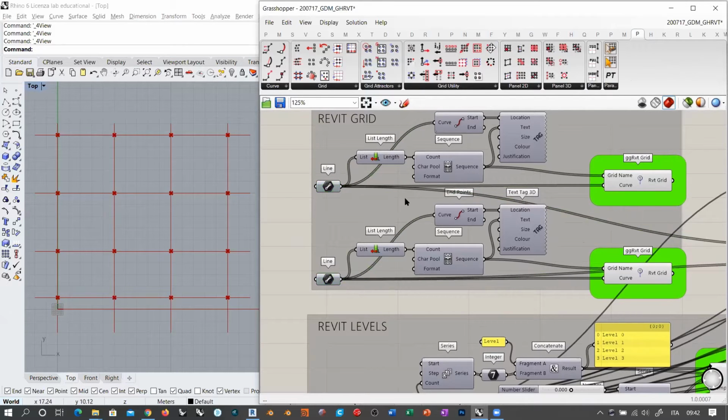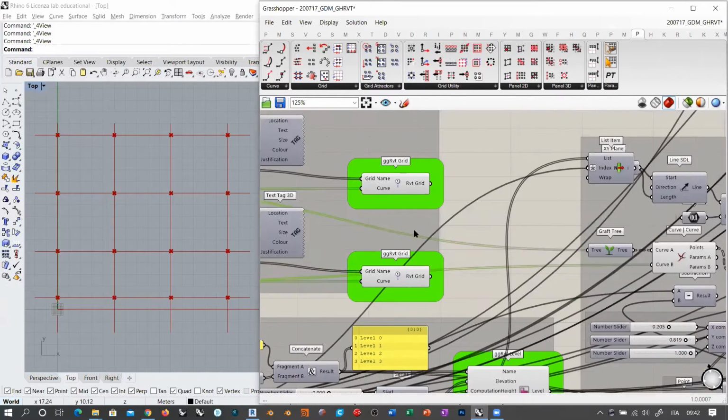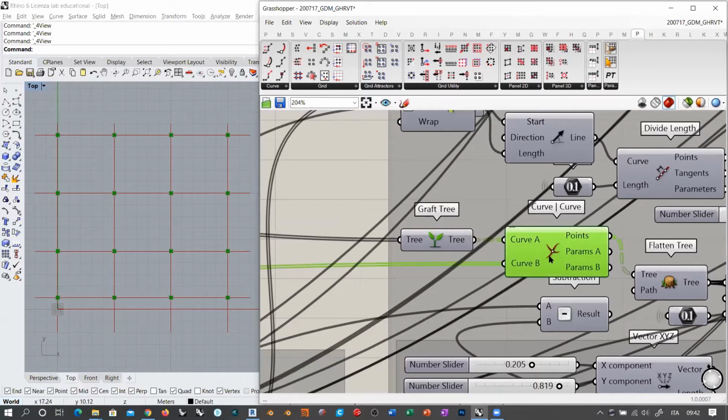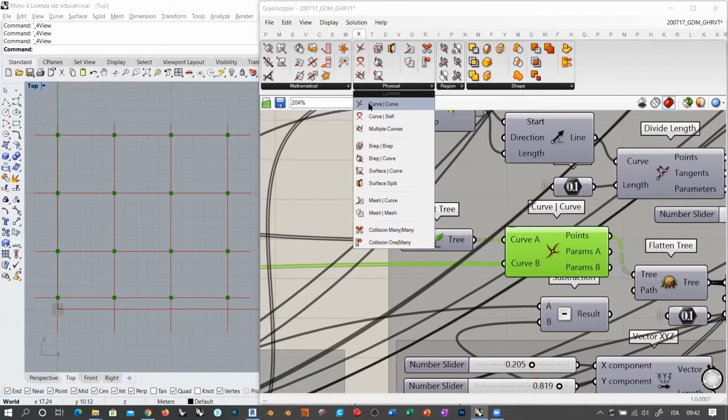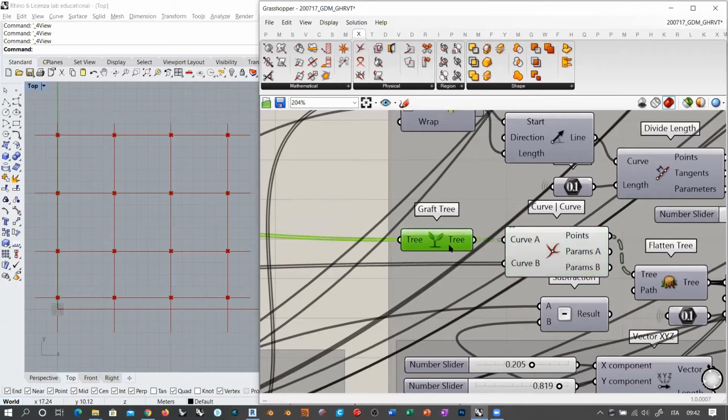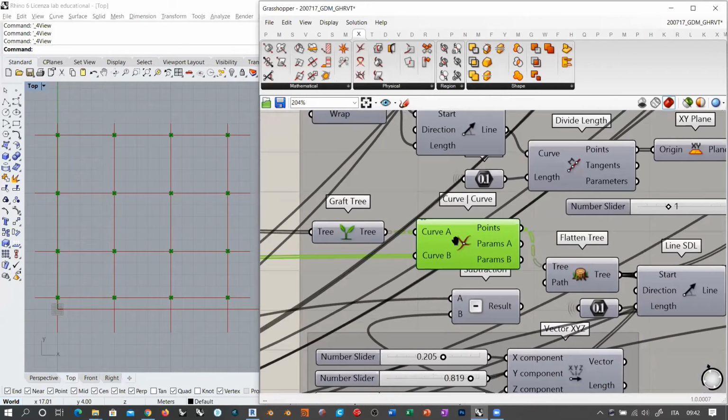But anyway, you take these two sets of lines and you calculate the intersection, which are physical intersections. So once again, you're going to intersect physical, and you will find curve. Remember, you must graft at least one of the two inputs in order to create the whole set of intersections. If you don't do this, you will have some intersection like one line with one line, then second line with second line, and you will have only this diagonal intersection. So that's why there is this graft here. So these are the intersections.